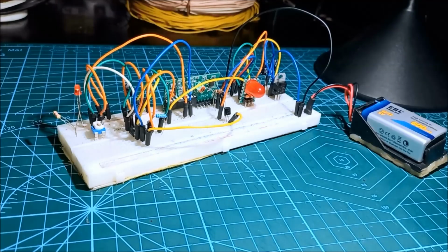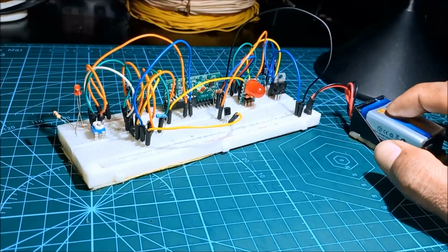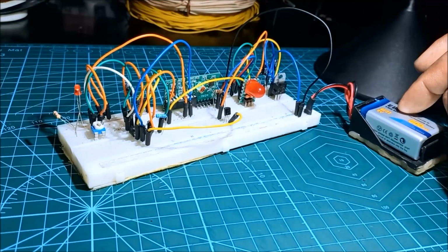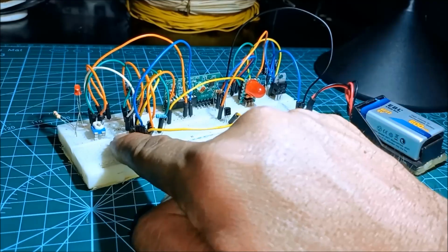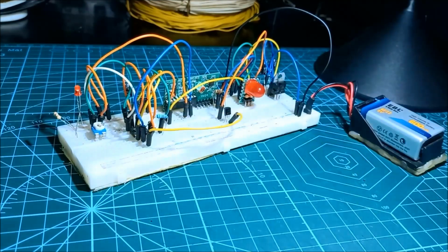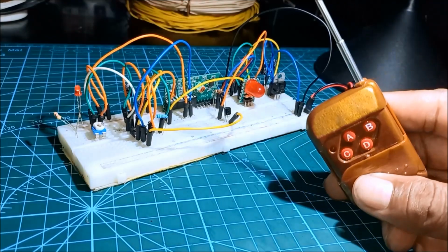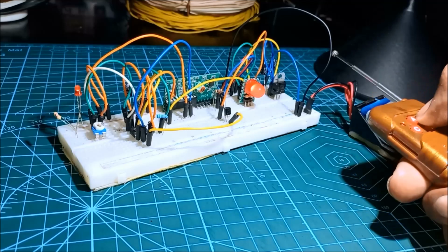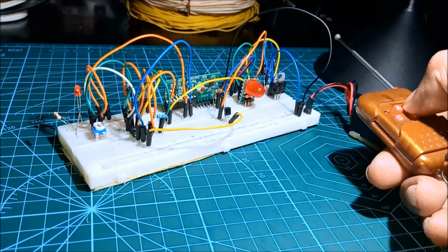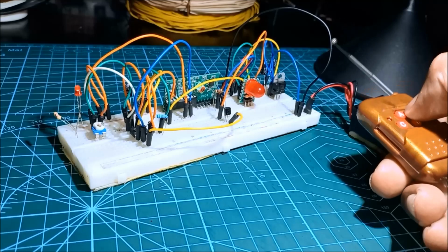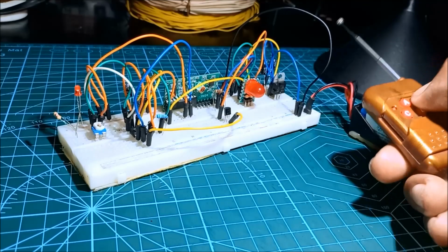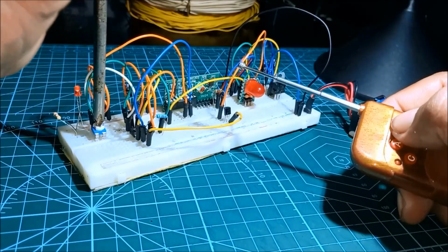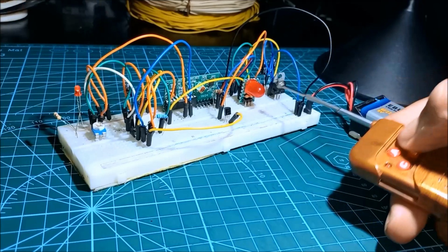This is now our circuit. We have the 9-volt supply, and then a 5 volts converter, converting 9 volts into 5 volts, and then we have this 555 timer. Press the button. Okay, it is a momentary switch. But because we have a new circuit, we're going to adjust a delay, introduce a delay.